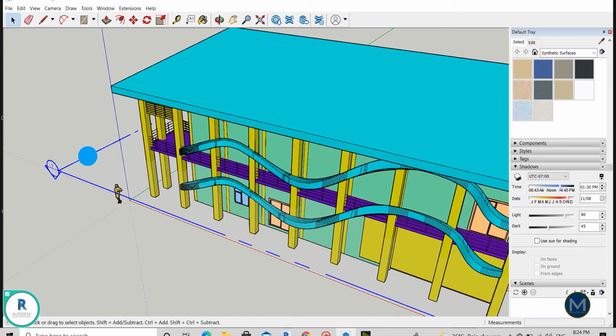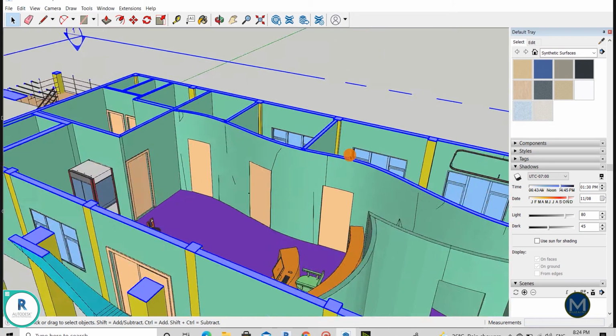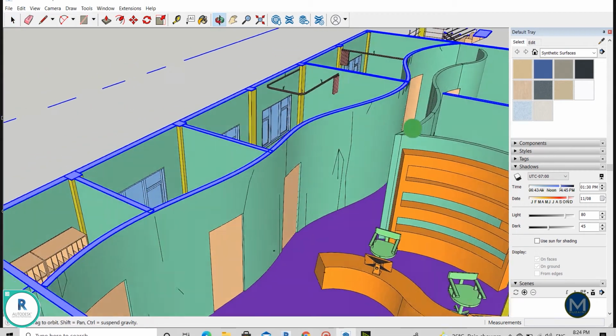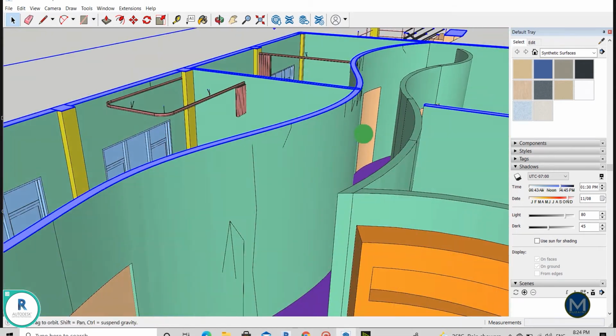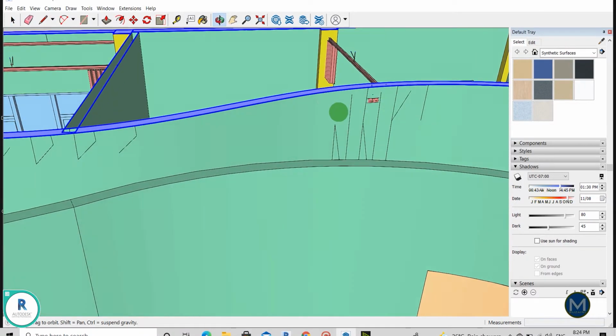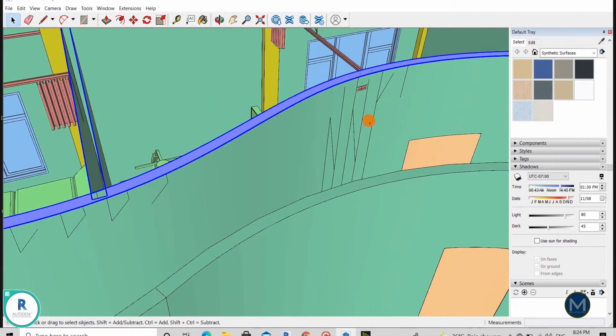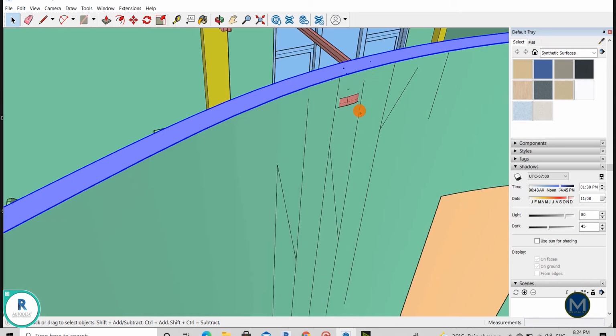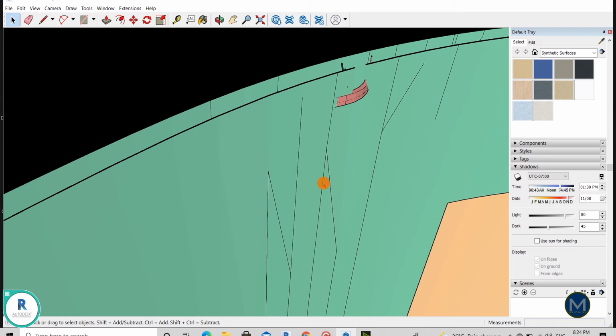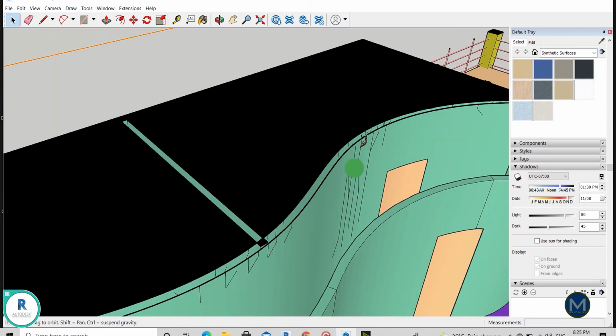Okay, so I just activate cut. As you can see here, we have lines as the wall is modeled using mesh in Revit. So when we export it, it becomes a set of lines. And worse, if you want to delete it, it will affect other components as well.